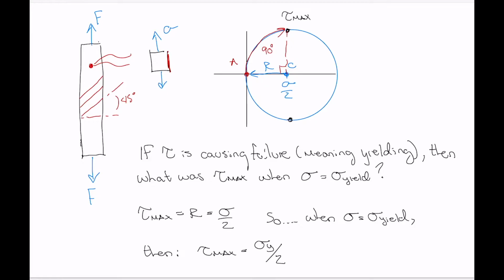And what the maximum absolute shear stress theory says is that we can take the right-hand side of this equation, the yield strength divided by 2, and say that failure in a ductile material will occur when that material is under a more complex loading situation, when the maximum shear stress reaches that value.